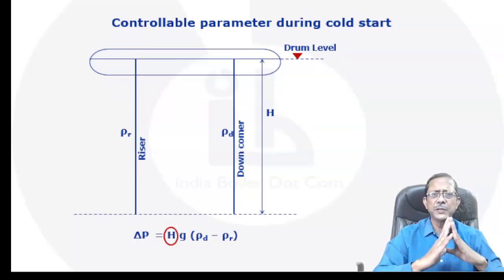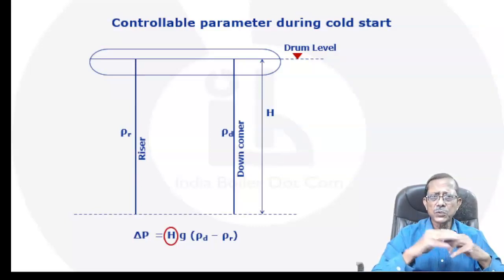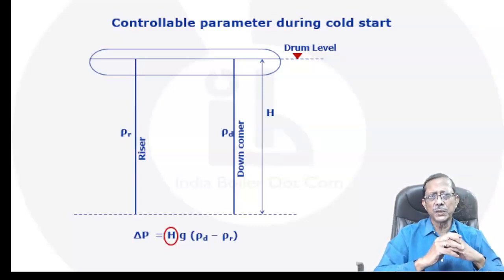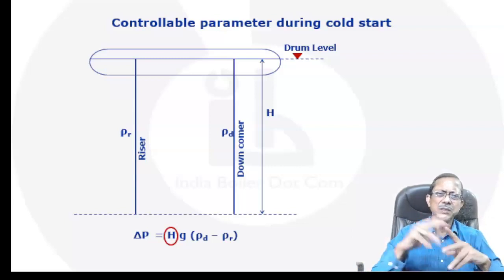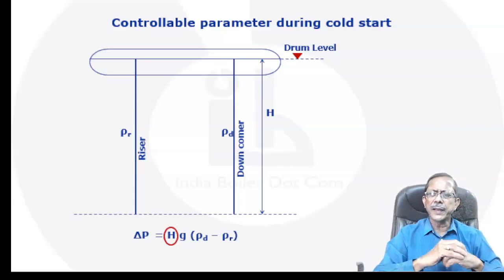It is very important to ensure the reliability of the system. So always remember this: maintaining the drum level, particularly at the time of cold start, is very important when it is being done manually. Once it comes in a three element system, then we don't have to worry about that. The swelling characteristics will be taken care of by the three element system.